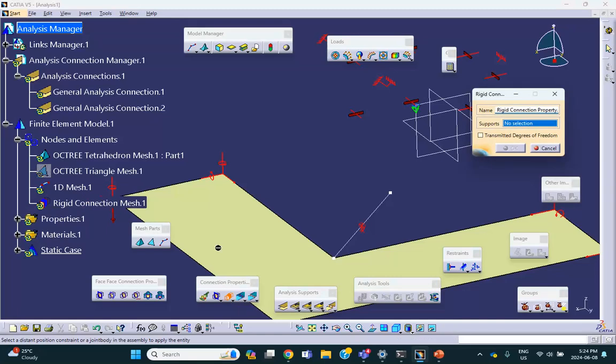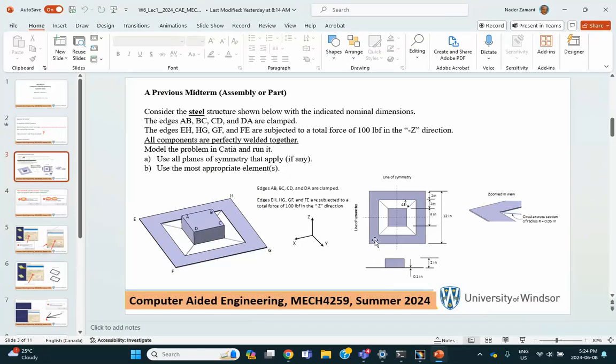You select this one, and all the degrees of freedom are transferred, because it doesn't say anything whether these are cable or not. And let me see on the statement. It doesn't say anything about these being cables. But if they're cables, remember, you have to release the appropriate degrees of freedom. Yep. Doesn't say that.